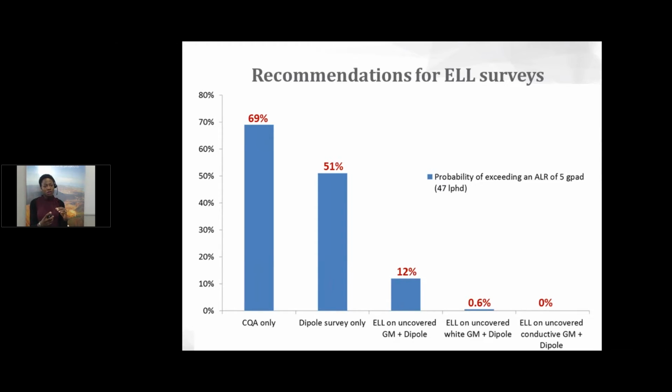Now, I'll talk about allowable leakage rate for a second here. Allowable leakage rate, or action leakage rate, is not a permission to leak or discharge materials into the environment. This is only applicable to a double barrier system where we have a leak location layer between the primary geomembrane and secondary geomembrane. So the allowable leakage rate is the maximum leakage that has been specified for that leak location layer. When you have a single barrier system, it's an absolute zero leakage into the environment.